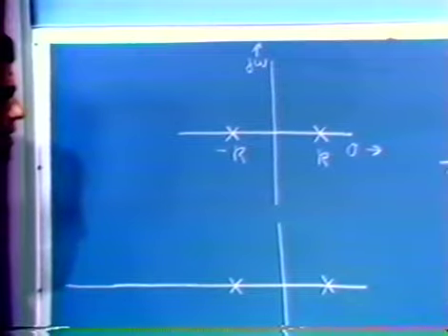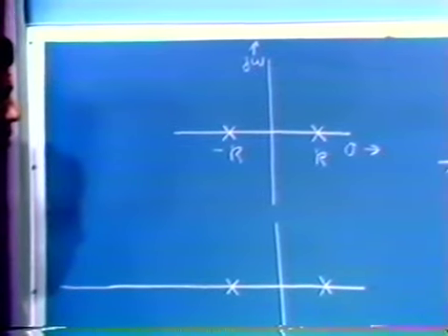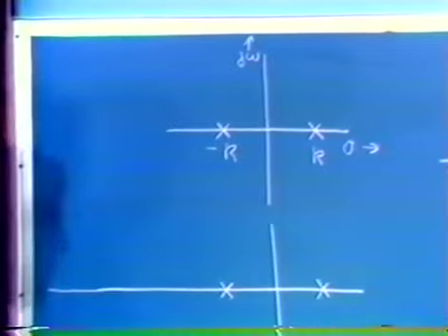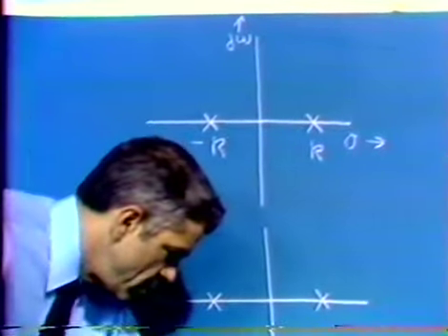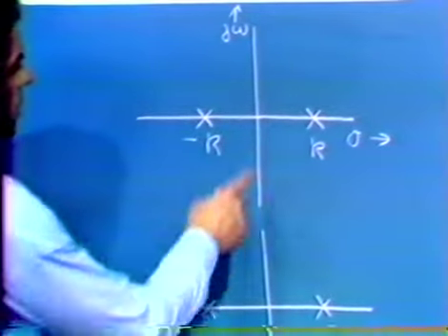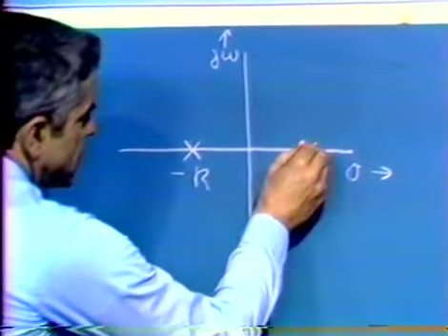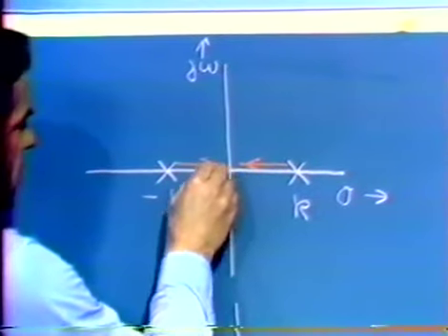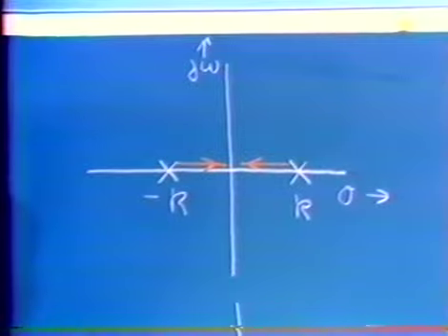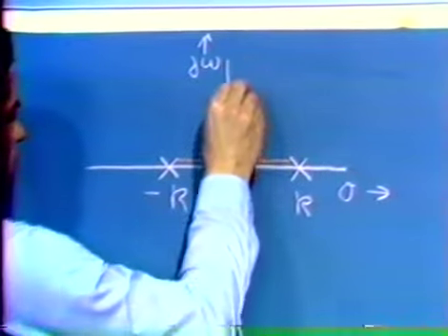Let's see, if we first of all simply surrounded the ball magnet dynamics with a pure gain, in other words, if A in our overall system block diagram were frequency independent, that doesn't work, because as you remember, the root locus diagram for this sort of system would simply be two branches which came together. They would meet at the arithmetic mean, which in this case happens to be the imaginary axis, and then branch off